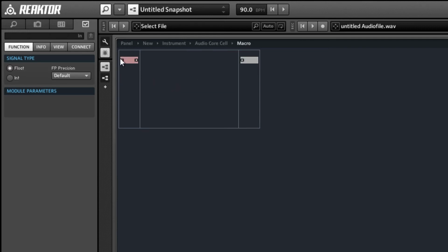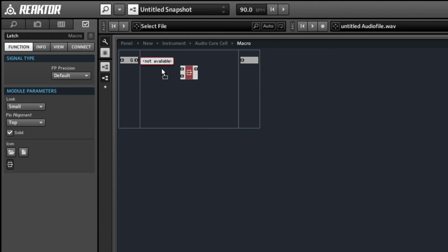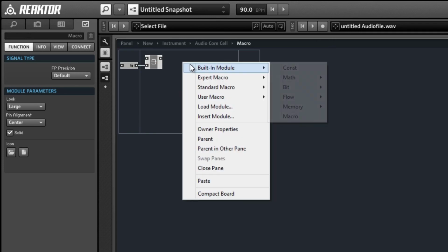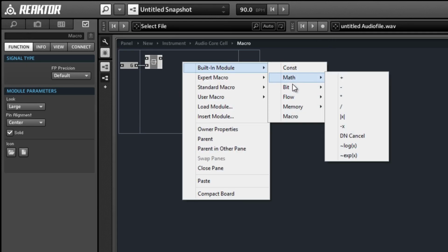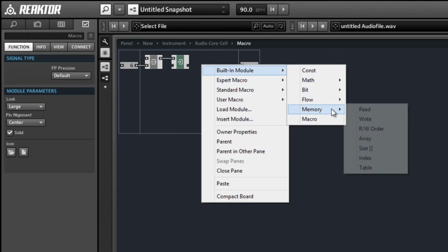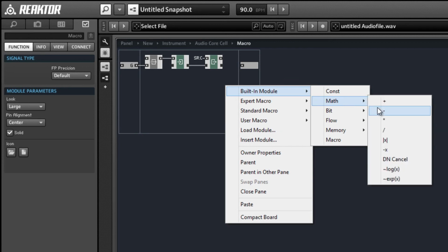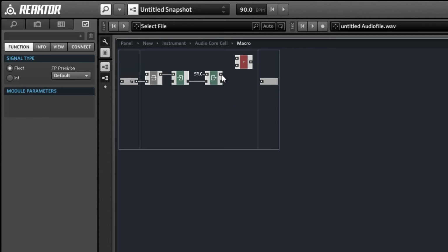So to start out on some familiar territory, I'm just going to build a simple counter, and this counter is going to reset to 0 every time we get a gate signal, and we'll be counting time in seconds. So basically, by resetting with each gate input, we're starting over at 0 whenever the gate turns on or whenever the gate turns off. And so we'll be either counting time for the attack decay period of the envelope, or we'll be counting time for the release period, depending on whether the gate is on or off.